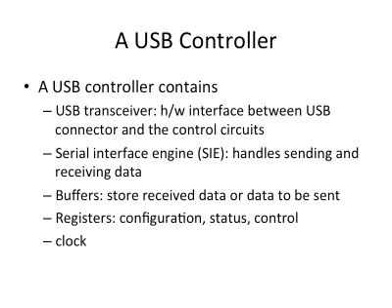In addition, buffers are often included so that you can temporarily store the received data or the data to be sent out. Because you are talking about high-speed transfers, the speed can go up to 480 megabits per second, or even 4.8 gigabits per second for USB 3.0. So the buffers are important to handle the data transfer spikes.